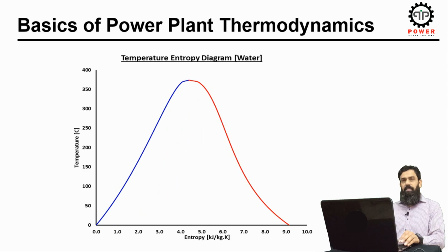Now let's expand and discuss all these terminologies and concepts that we have discussed so far through an example of a piston-cylinder arrangement, in which the water has been placed at a temperature of 20 degrees centigrade, and this arrangement has been placed in a normal atmospheric condition with a pressure of 1 atmosphere acting on the face of the piston, and the weight of the piston is also constant. Heat at a constant rate is also being applied to, or absorbed by, the system. The same pattern has been plotted on the temperature entropy diagram.